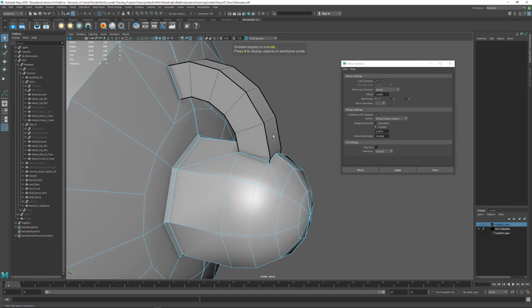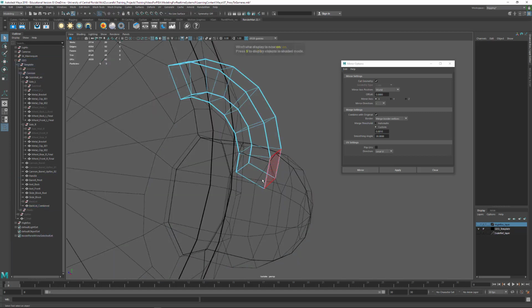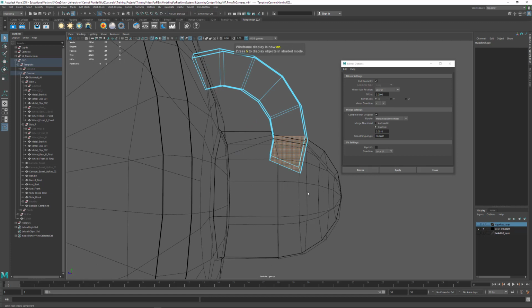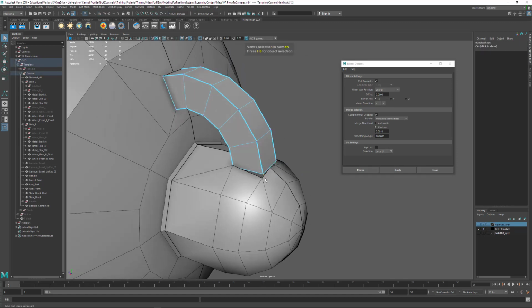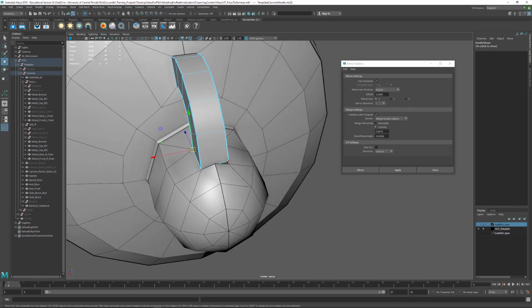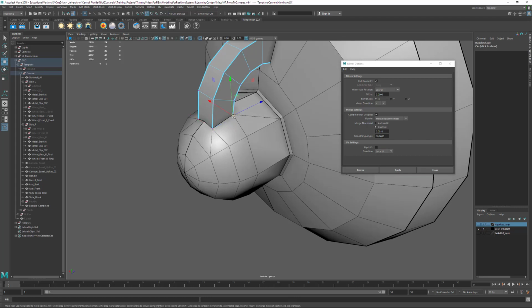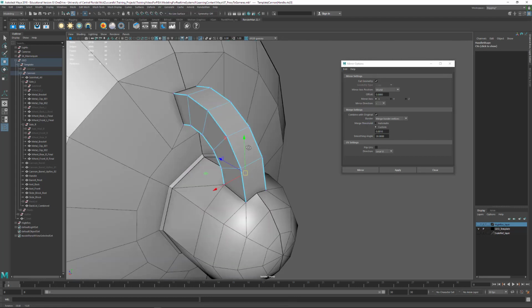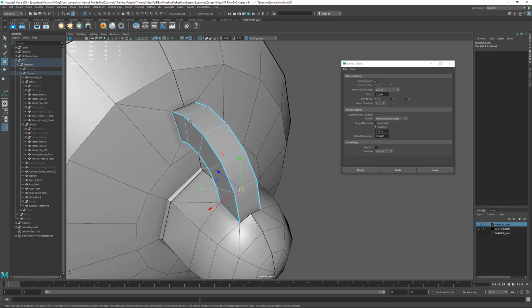Now for this model, looks like we don't need the bottom of this. Tap 4. So let's just get rid of this right here like that. Let's take these verts, F9, and I'll move them and snap them to this here, snap this here. I'll take this, snap it here, and this one, snap it here. And I think I'm going to just run a split down the center of that. That will probably make life a lot easier for the top and the bottom.